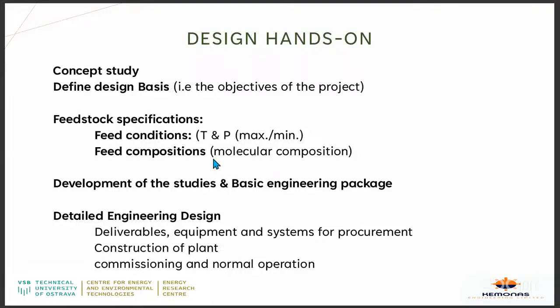Another thing that's not listed here in the design scope would be the over design and also the minimum operating condition. Usually the practice is around 10% over design of the plant, 10 to 20% over design of the plant, and this is to allow for increased production. Okay, and also the lower limit will probably be 50% of production.